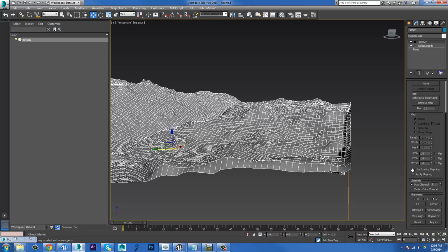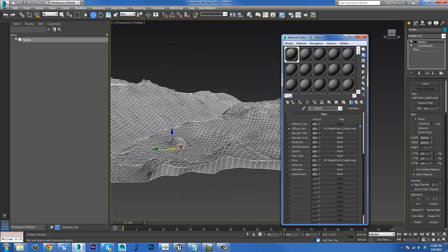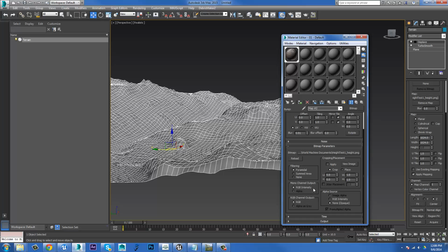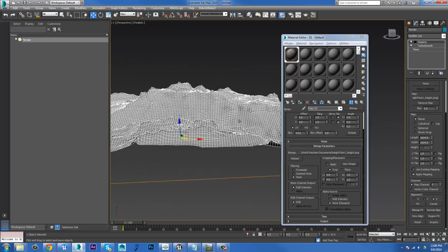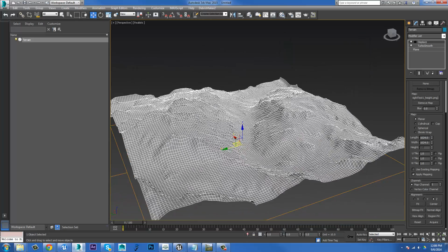I'm wondering if that's apply mapping, and I'll fit it. Maybe it's to do with the mapping. I've fixed this problem before, but I'm trying to remember. They do a blur on it. And RGB intensity, no filtering. No filtering, yes. We turn the filtering off because it'll blur the edges and make those numbers a bit skewed.